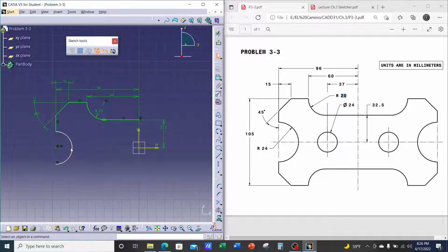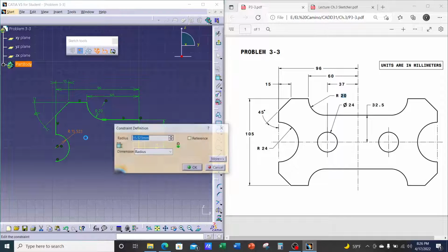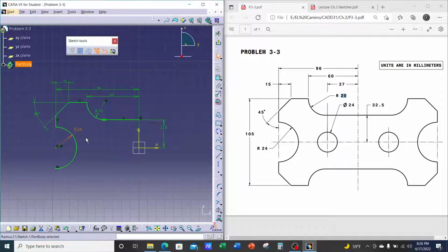So we have green. Now the arc. So what's wrong with the arc? So let's pull on it. If I hold on to the arc, left mouse, click and hold, notice there's no radius. It changes in size. It's locked in as far as location, but it doesn't have a radius. So the radius is 24. Let's throw in that 24. And enter, and there it is.